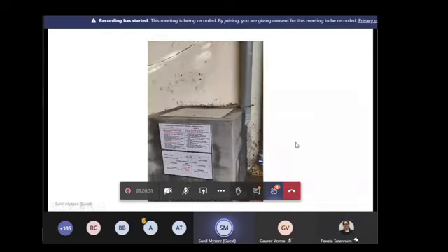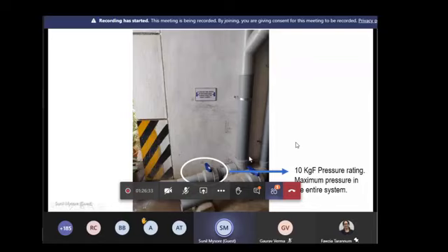Okay. So in that video, you saw a valve. The valve is a very important detail in the entire system. In a rainwater harvesting setup, the maximum pressure is on the valve because that's the lowest point in the entire setup, so all the water essentially comes there. Generally, I've seen people using very substandard material for the valve. Valves are pretty expensive components, and people try to cut costs here because they're more interested in aesthetics. So they use a very substandard valve.